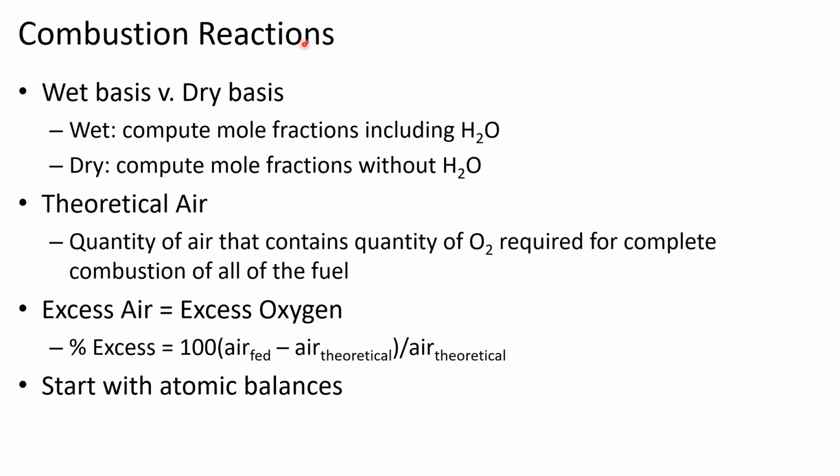Of course, with combustion reactions, we're going to have a whole set of new terminology to deal with, and those terms are summarized here. The first and probably most important one is that we'll make a distinction between whether compositions are specified on a wet basis or a dry basis. The difference is stated here. When compositions are specified on a wet basis, that means the mole fractions have been calculated, including water in the calculation. When mole fractions are specified on a dry basis, that means that water was not included in the calculation. And we're going to see an example of this in the very first problem that we work.